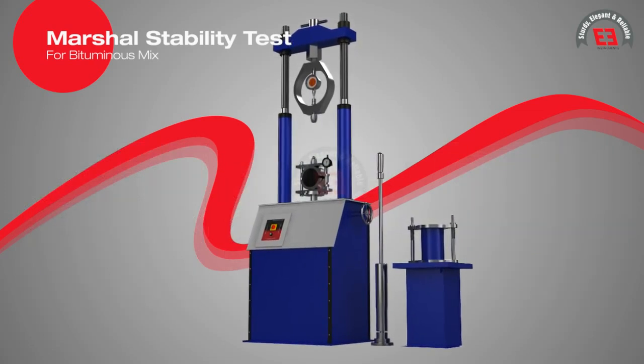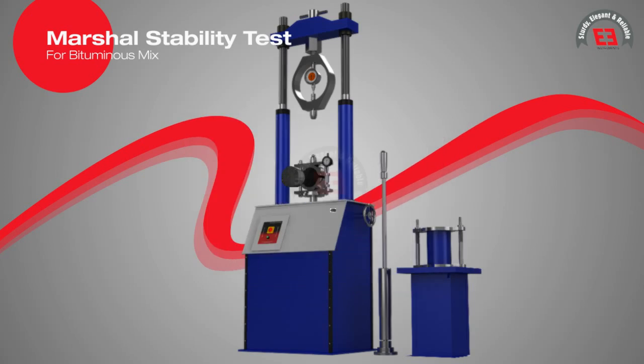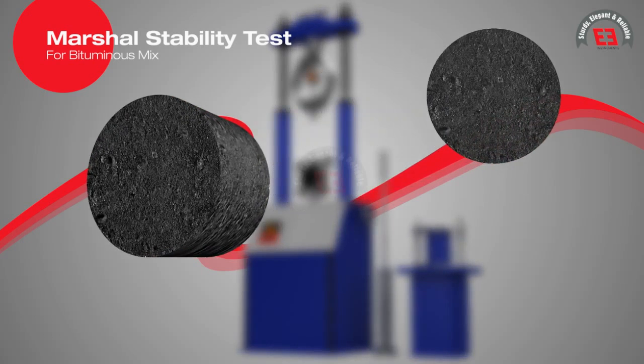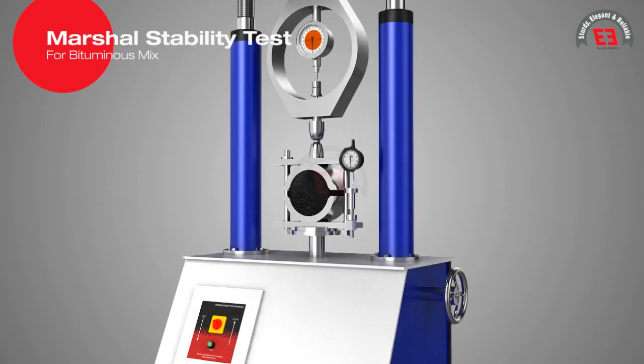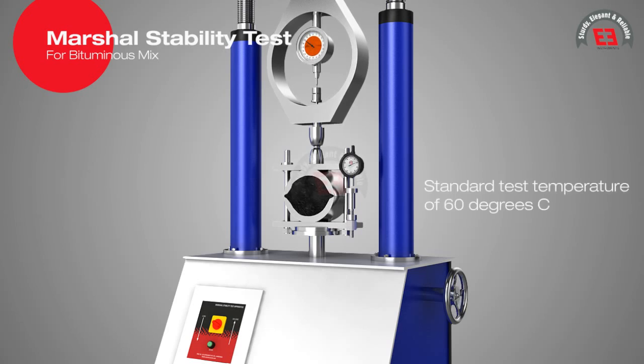Marshal stability test is conducted on bituminous mix specimen for designing of flexible pavements. Marshal stability test is conducted on a compacted cylindrical specimen of bituminous mix of diameter 101.6 mm, having thickness of 63.5 mm. The load is applied perpendicular to the axis of a cylindrical specimen through a breaking head assembly at a constant rate of travel of 50.8 mm per minute at the standard test temperature of 60 degrees Celsius.